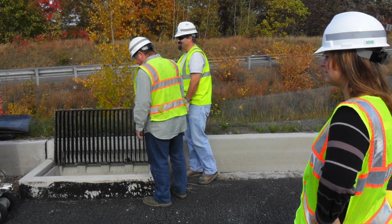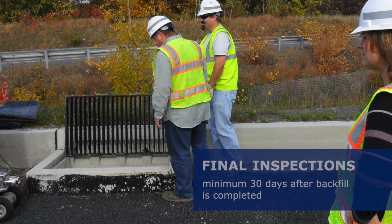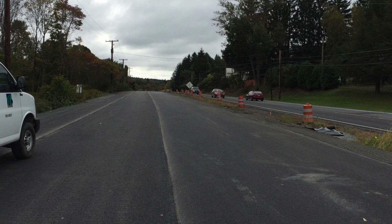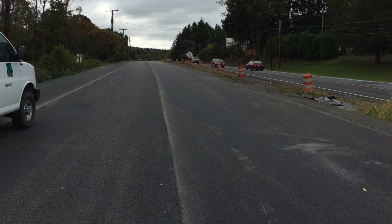Key requirements to remember are that final inspections must be completed a minimum of 30 days after pipe backfill is completed, and Form CS601 is used to document these pipe inspections. If the final wearing course is placed more than 30 days after the pipe backfill is completed, this final inspection must be performed prior to placing the final wearing course.